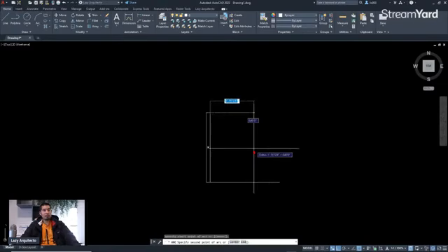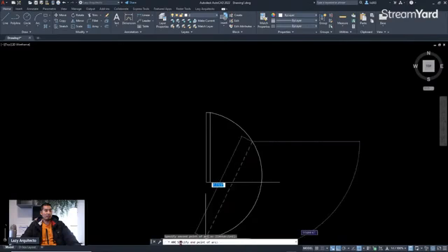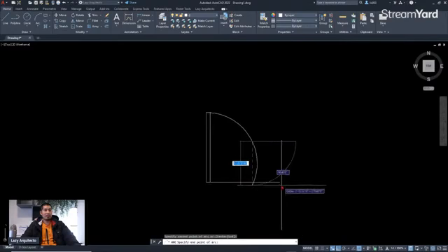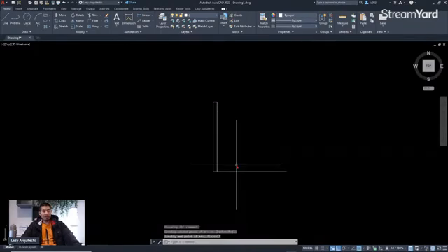At this point, I can simply click like that using the command line. But if you want a perfect door, it's better to draw a circle. So I'm going to draw a circle. Again, this is another command. Its shortcut is CI for circle, and press enter.